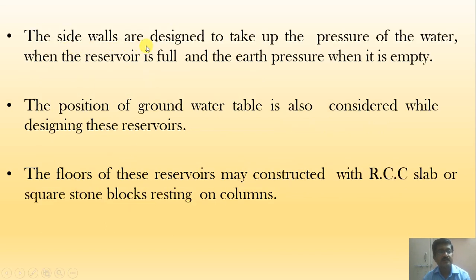The sides of the wall are designed to take up the pressure of the water when the reservoir is full, and the earth pressure when it is empty. Remember, two points we have to consider in the design: when the tank is full, the water pressure will act on these walls, and when the tank is empty, due to the height of that underground reservoir, the soil pressure or the earth pressure may act.